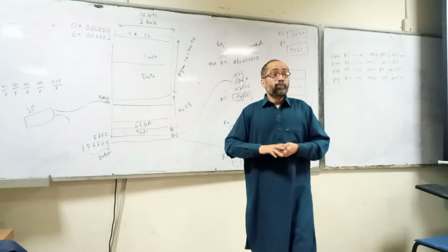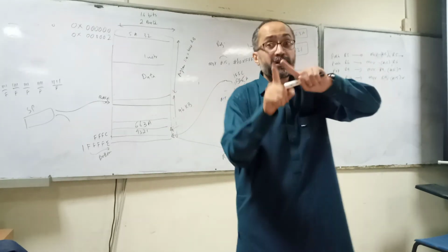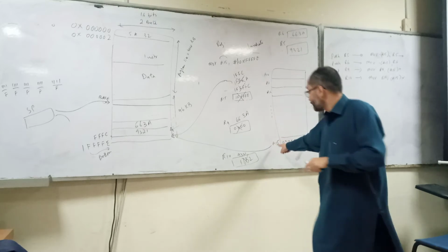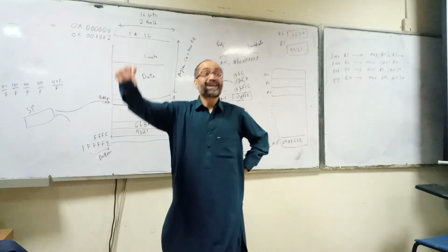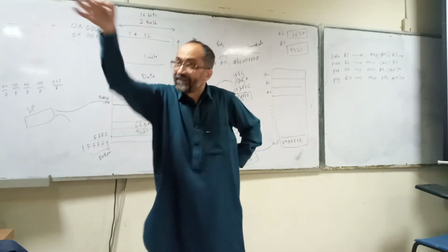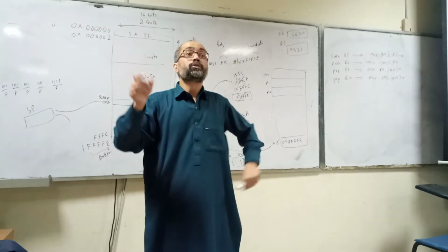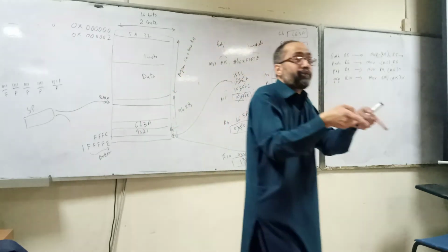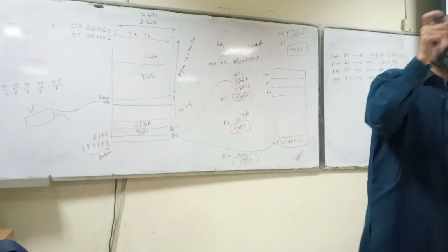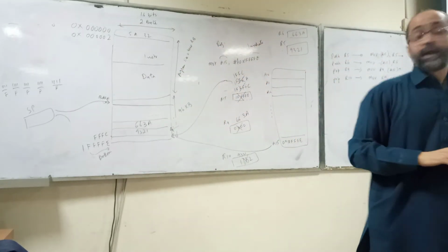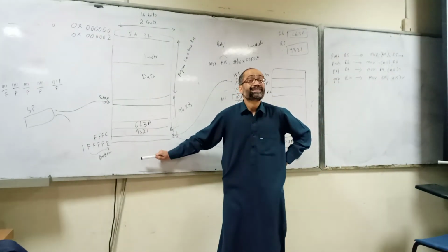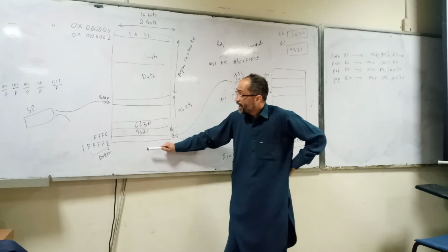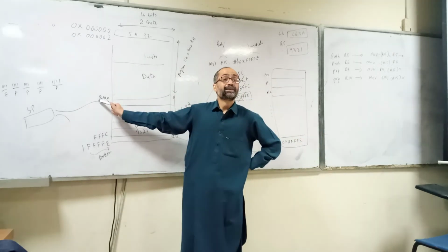So actually, before performing a push or a pop operation, first you should compare the content of the address register A15. If A15 is equal to the bottom address, it implies that the stack is empty. So you need a check. If you want to have a fail-safe program, first you need to check whether the stack is empty. If the stack pointer is pointing to the bottom address, what does it imply? The stack is empty.